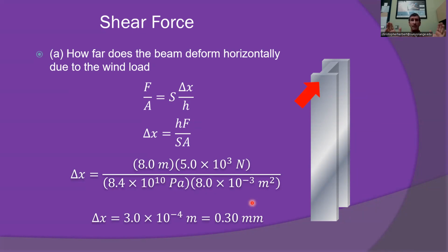You can't make the building completely brittle because if the steel is too brittle of a material, it might be stronger initially, but with thermal cycling, it getting warm, cold, and movement due to different forces, brittle materials tend to get fractures in them, whereas materials which are a little bit softer, which actually bend and don't break, might be more appropriate for such a structure.